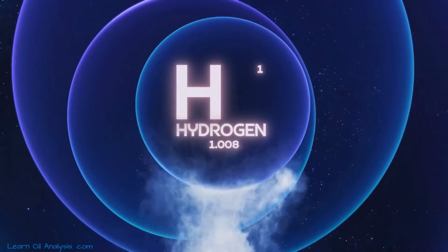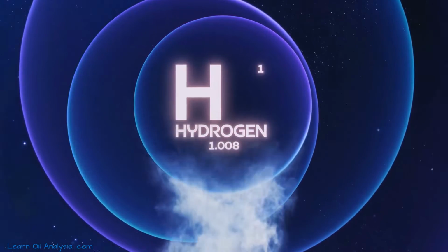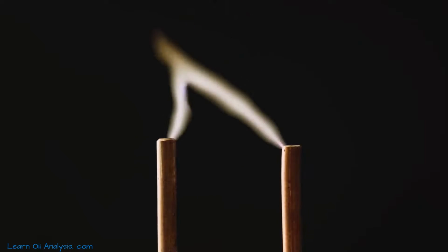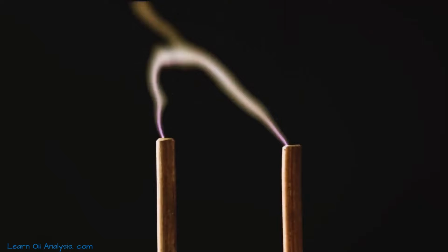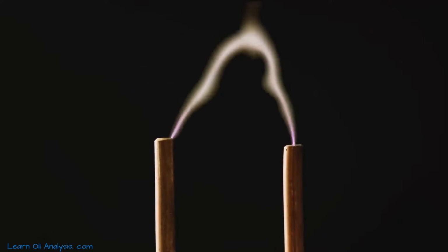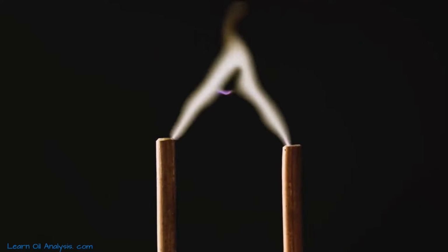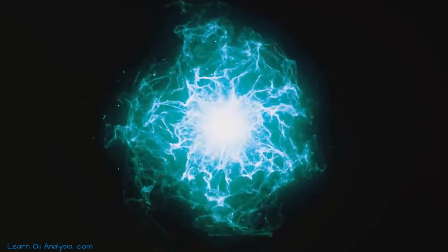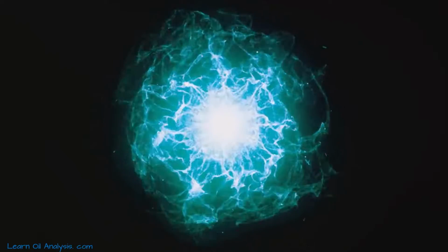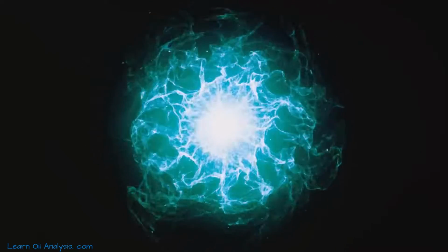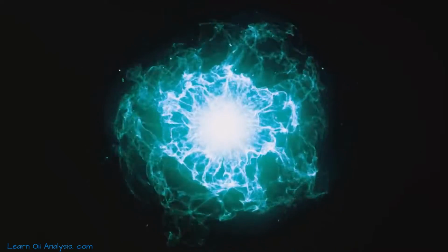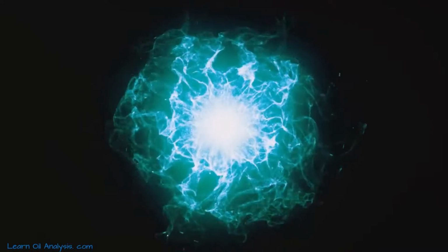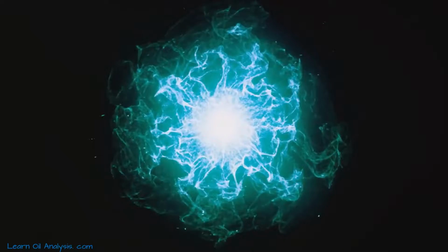So, if you detect a rise in hydrogen levels in your DGA results, this could be a sign of a partial discharge fault. Now let's look at high-energy discharges and arcing. This type of fault is more severe than a partial discharge and suggests the electricity is jumping between metal contacts, causing a continuous arc. It's typically characterized by the presence of both hydrogen and acetylene. Arcing faults can be quite damaging and are often a sign of severe electrical stress within the transformer. Acetylene, in particular, is a potent indicator of arcing.